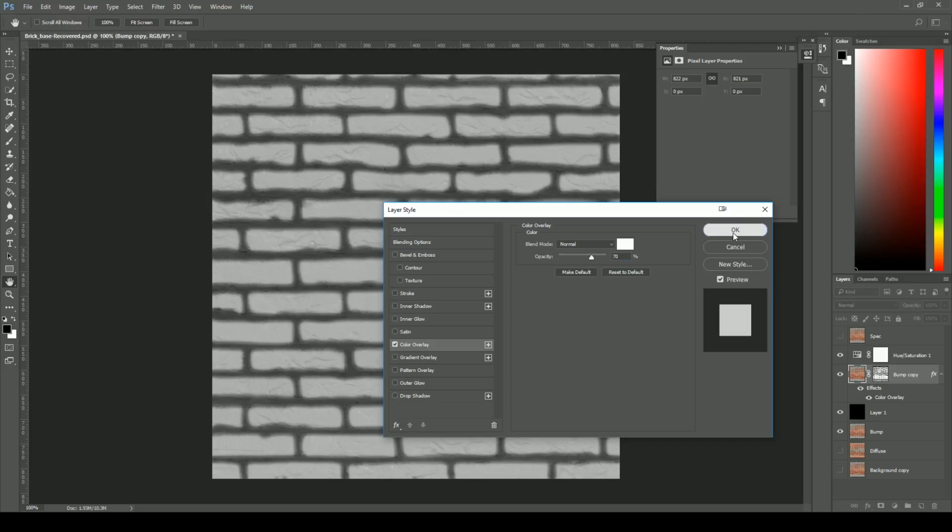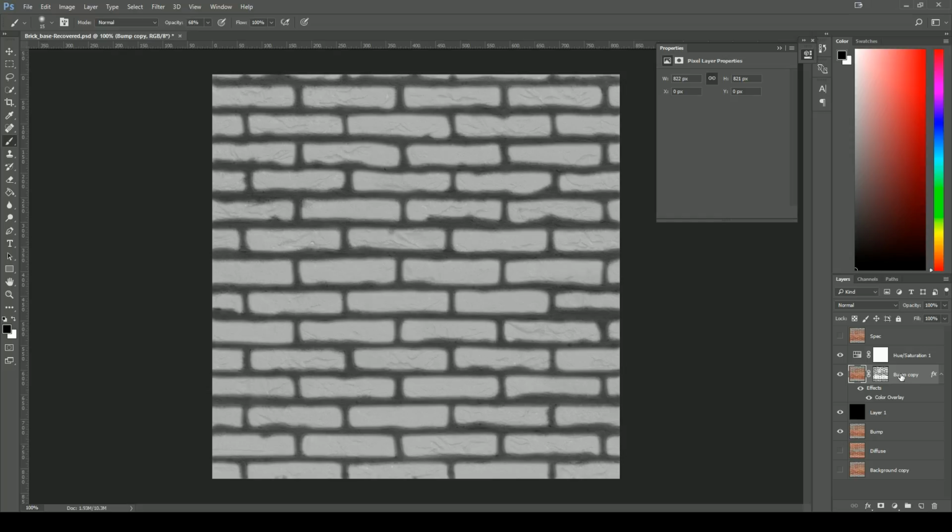What I'm going to do is actually make this not a bump map. I'm going to make it a displacement map and just demonstrate how you use displacement maps in Maya 2017. I'm just going to use Arnold, the default renderer in 2017. I definitely prefer RenderMan. It's a much more powerful, very nice renderer. It's quite effective. I think RenderMan's probably the way you should be going as much as possible if you can, but since Arnold is the default renderer in 2017, it's probably worth demonstrating how that works. And I'd like to show you displacement mapping.